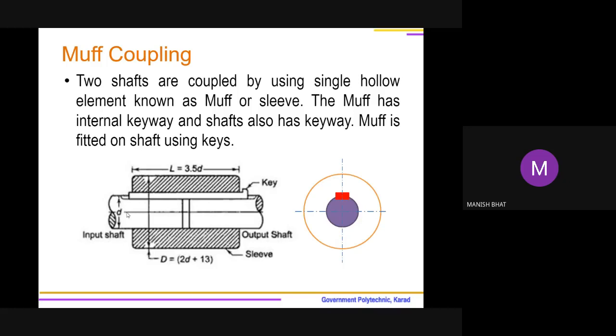Both shafts are aligned, their axes are aligned, is it right? In side view, you can see the shaft is carrying some key here. Key is mounted. So a rectangular key or say flat key is mounted. Slot is provided. Are you looking here? Slot is provided on both the shafts. Slots are matching and driven inside is a key. So a jib headed key is used.